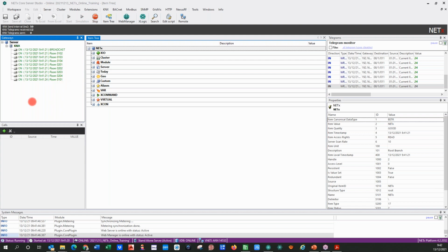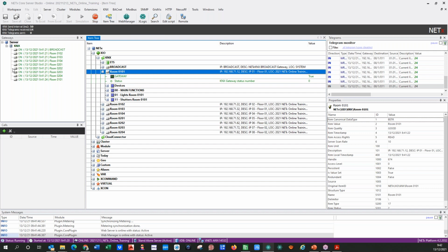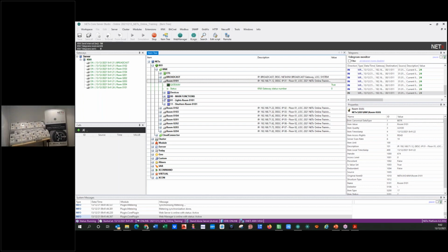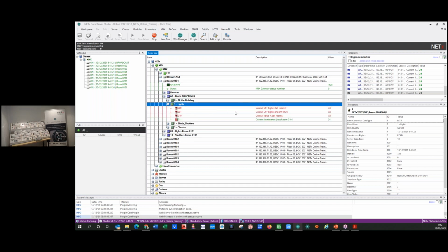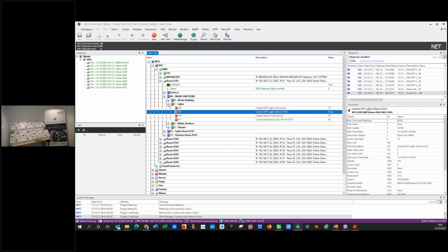This is real. And I can show you it's real because the first practical board is real, using these addresses. So I can show you if I turn on the camera for a second. The first is the bottom left practical board. So I have chosen here, for example, the main functions for the lights, and I send a telegram, send value 1 to this, and I force a value for this. So I am online. I've pressed a 0 and I say, okay, all this off. So we have the control for all this.